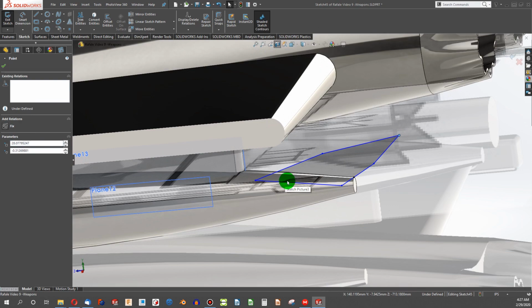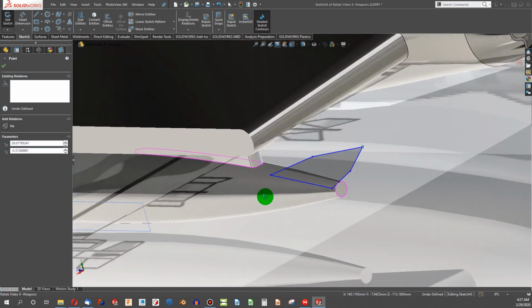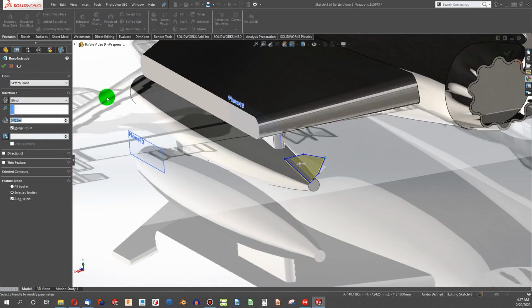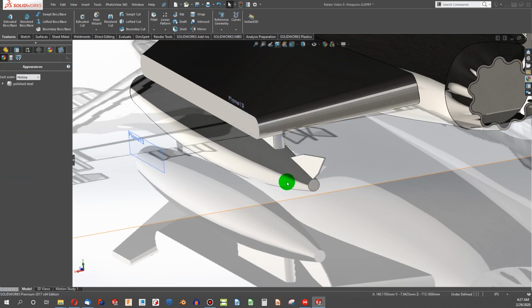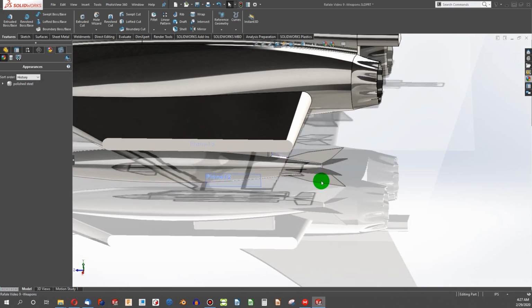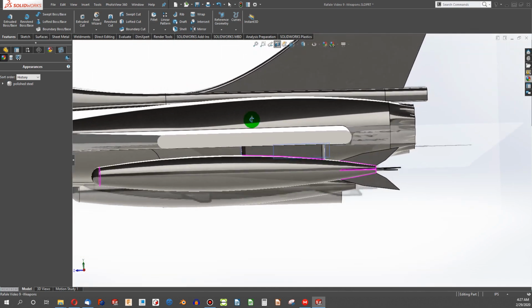After making this once, I'm right now in the mood to be a bit more creative than I have been. We'll extrude that again. Best practice is to fully constrain the sketch, but you get the idea. Let's set the blind to mid-plane. And let's do circular pattern. Our direction, I'll use this circle, and it fills in our fins. There we go. Kind of a wild fin.